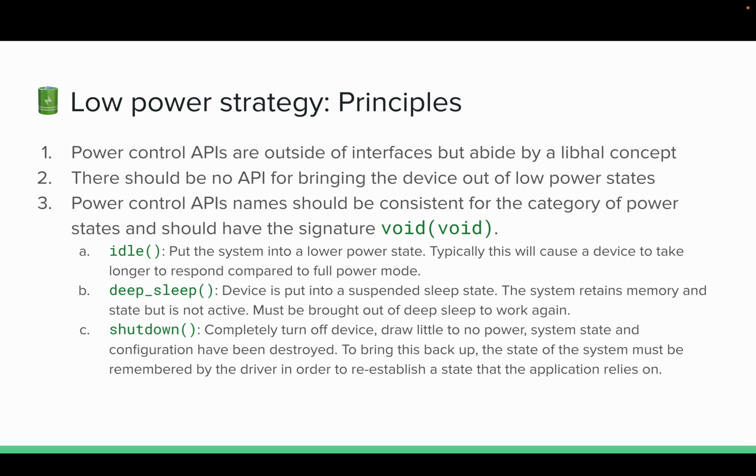So there can be an idle function, which puts the system into a low power state. The idea is that if you put your device into idle, it's not as active anymore. It'll draw less current, maybe not the lowest amount of current, but less. But if you try to interact with it, it'll come right back into active mode. You may ask yourself, why wouldn't we always just keep it in idle? Which you could. You could have it automatically always idle after you do any operation.